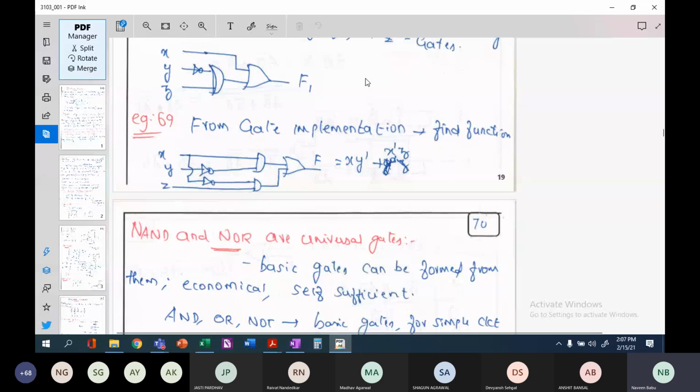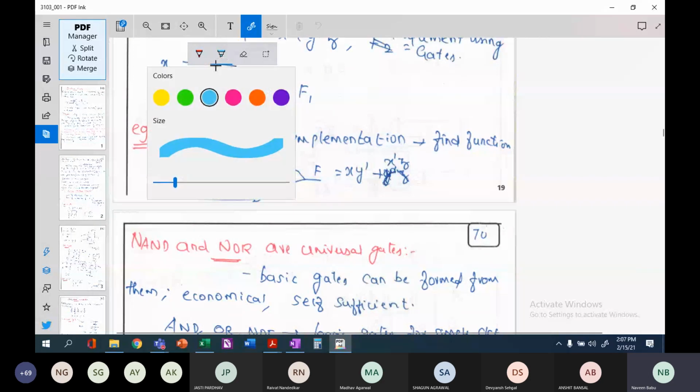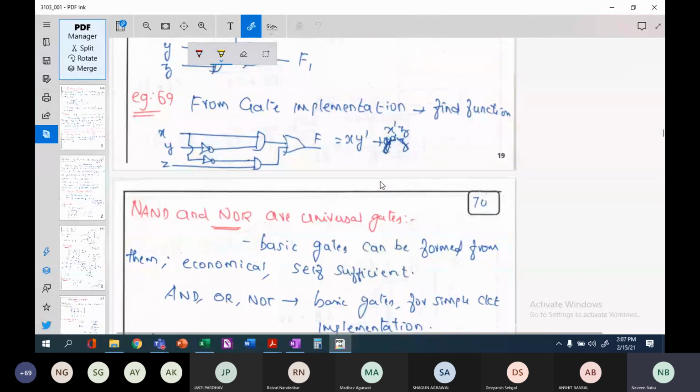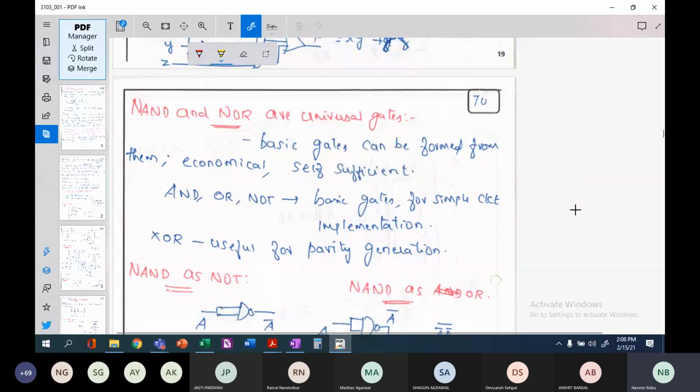Whereas if you are using AOI gates, you will be using an IC with AND operation, an IC with OR operation, and an IC with NOT operation. Even in case you are using an XOR gate, then you will use a different IC. Each IC will cost differently, and at the same time there will be a lot of unused gates inside those ICs also, which you will not be implementing for your actual functions. So those ICs will just occupy space.